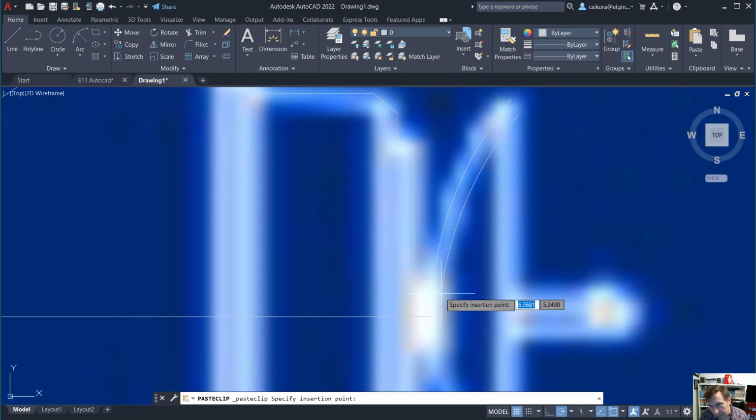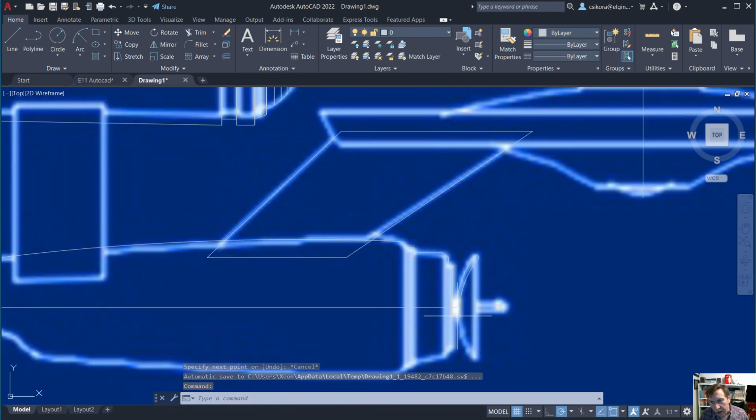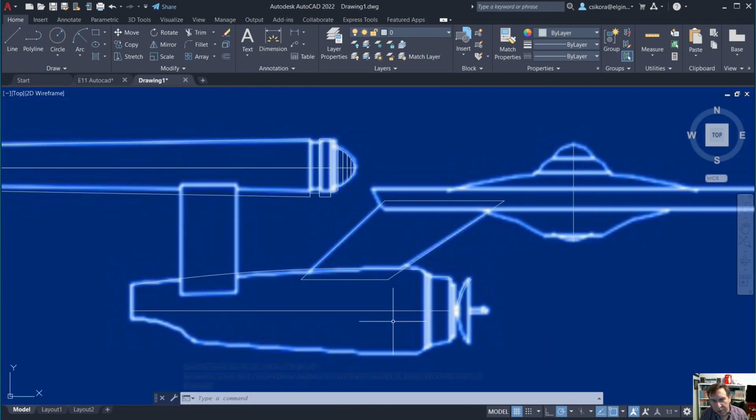And I don't want it to snap to anything necessarily, but that looks pretty good. I'm going to go to the line tool and close that little gap at the top. Escape, hit Enter again, and then we could actually, if we want, bring it right there or change it. Okay, so now we could join all that.